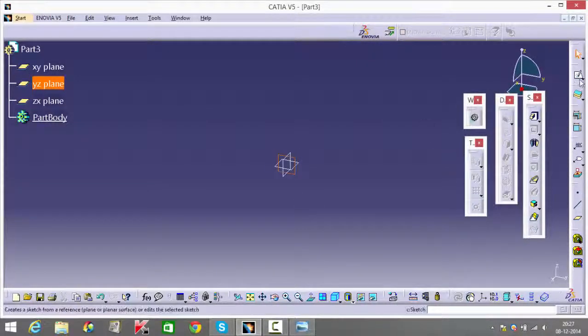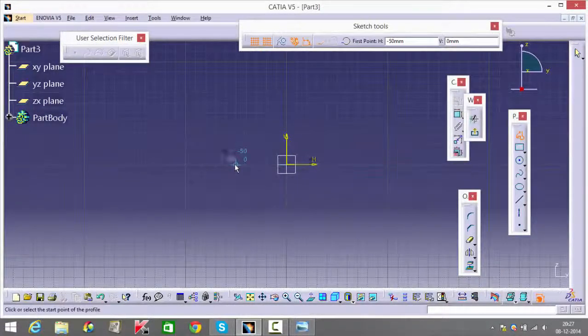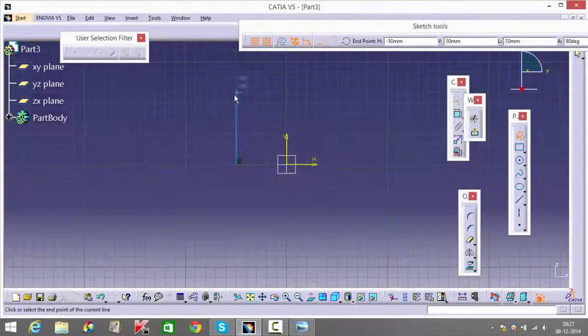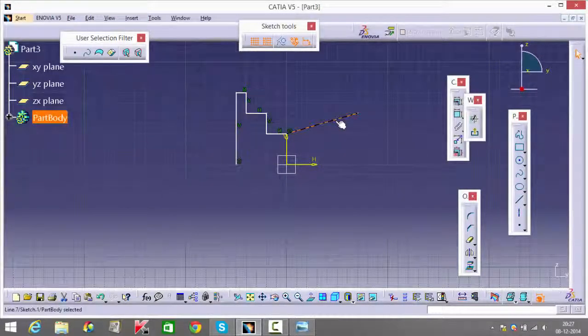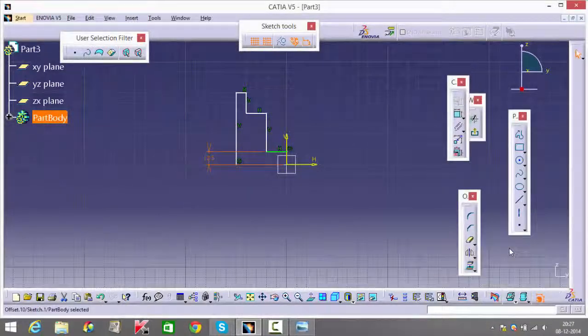What we're basically going to do is make a shaft option. I'm going to do that by selecting my profile. I'll just make a rough sketch of how my figure is supposed to look. I'm going to do till there, and just delete this remaining portion. I know this distance is given to me as 25, sorry, it's totally supposed to be 25. So since I'm using a shaft option, it's going to be 12.5.